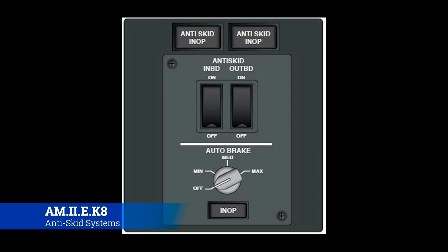Okay, so anti-skid systems not only detect wheel skid, when it's sliding around, they also detect when wheel skid is imminent. So it knows that there are preconditions to a wheel skid, and it's constantly looking for them and trying to curtail it before it ever gets going. It does this by automatically relieving the pressure of the brake pistons of the wheel in question, by momentarily connecting the pressurized brake fluid area to the hydraulic system return line. So basically, it's opening a valve and allowing the pressure to come off of the brake pistons, so that the wheel can spin rather than lock up and skid.